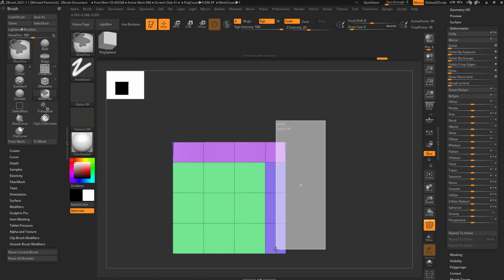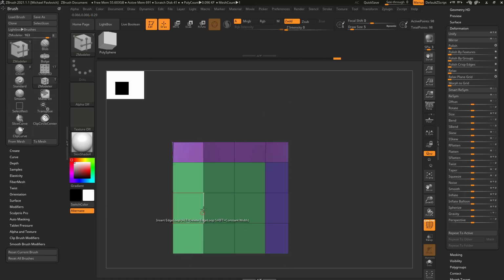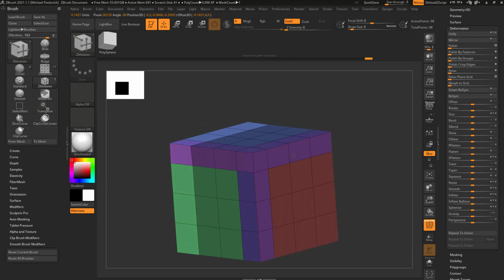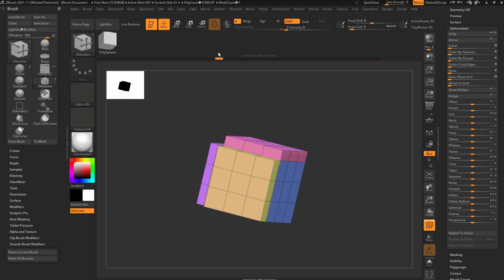And then over here we'll hold down Control Alt, we can clip these, and then over here we can hold down Control Alt, and we'll do W, Control Alt Shift to set that pivot, and then we'll use Z scale to just scale those along a flat island there. So let's go ahead and undo back.